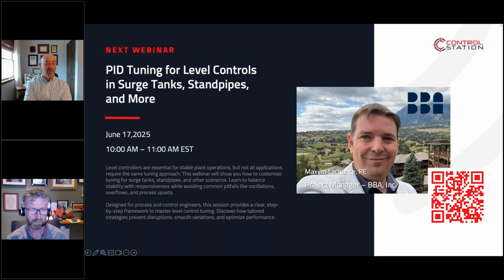Asking those questions at design time is where I would put more emphasis at the beginning of the process. Make sure I've got an actuator that's big enough, make sure I've got an air supply that's big enough, make sure I've thought through the selection of valve seat materials, for example, for how that's going to impact stiction, as it relates to the type of process fluid going through there.